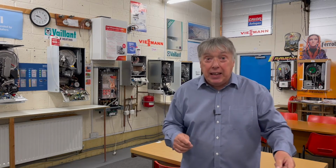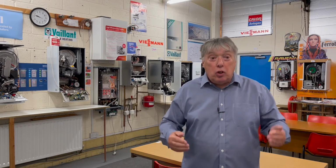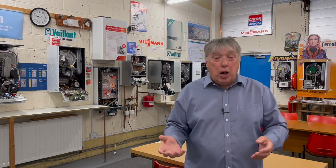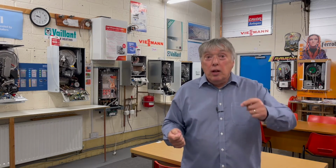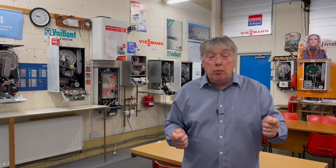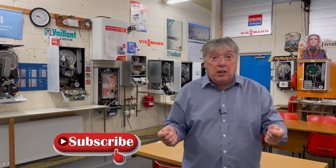Even after lagging, it's still going to lose a lot of temperature, so you have to compensate for that. A normal 3-bedroom semi is around 14-15 kilowatts. If you live in a park home or a 2-bedroom bungalow, you might be nearer 9. So having a boiler that's outputting almost 3 times the amount is a complete waste of gas, and